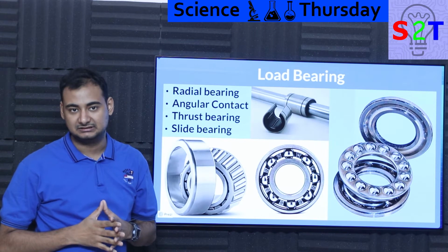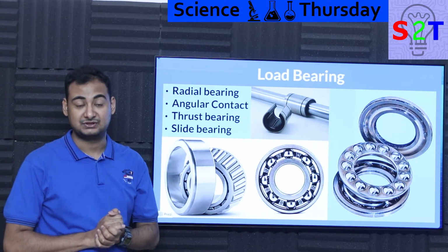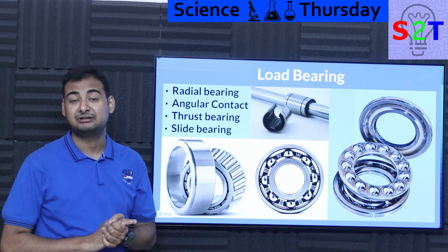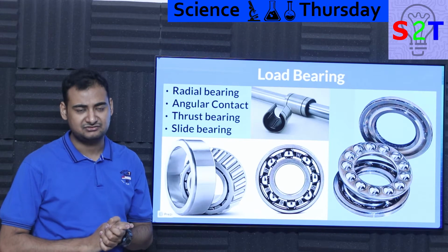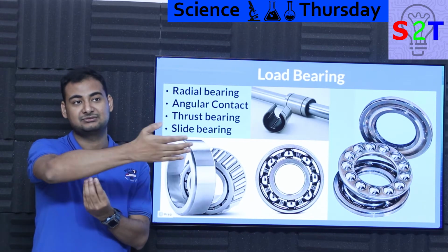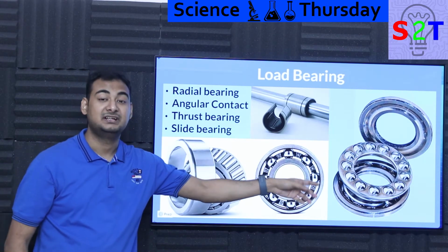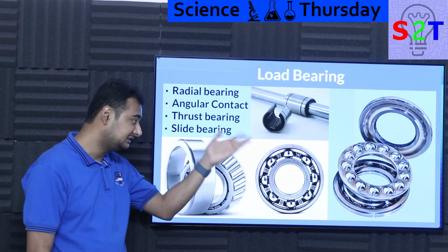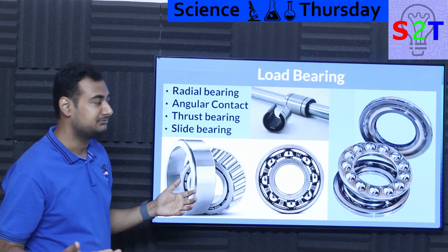Now thrust bearing is generally utilized in scenarios where you have big things moving on top of each other. The biggest example I could think of is battleships, where they have gun turrets which are hundreds of tons to 2000 tons, moving on a system. Even tank turrets start to look lightweight compared to that. So thrust bearings are utilized in those sort of scenarios. And generally they are roller bearings, because again, ball bearings may not have enough surface area to dump that load perfectly.